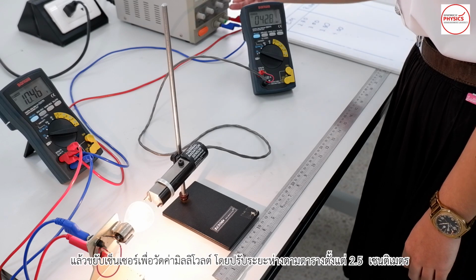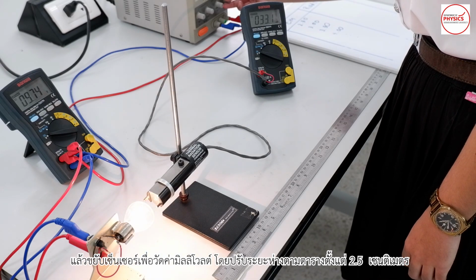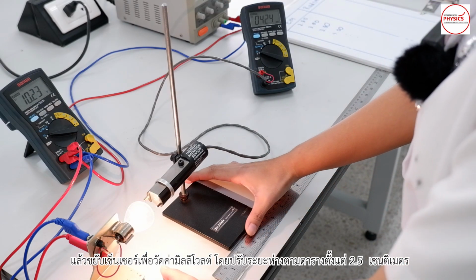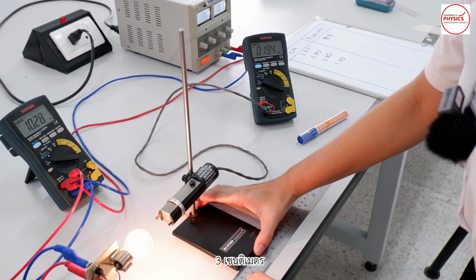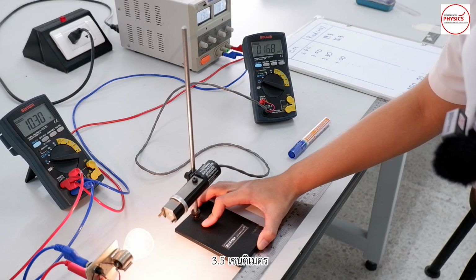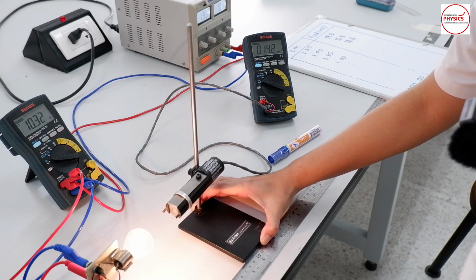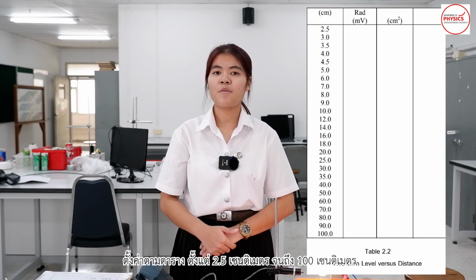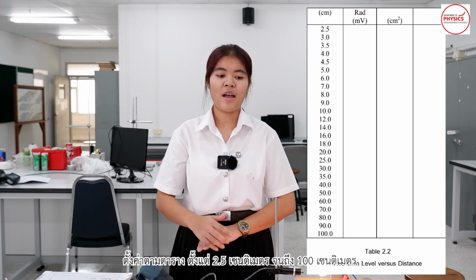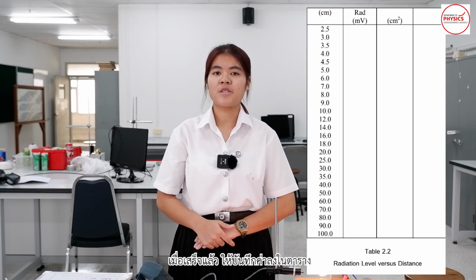and move the sensor to measure the millivolt value, adjusting the distance according to the table, from 2.5 cm, 3 cm, 3.5 cm, 4 cm, and so on according to the table, from 2.5 cm to 100 cm. Once done, record the value in the table.